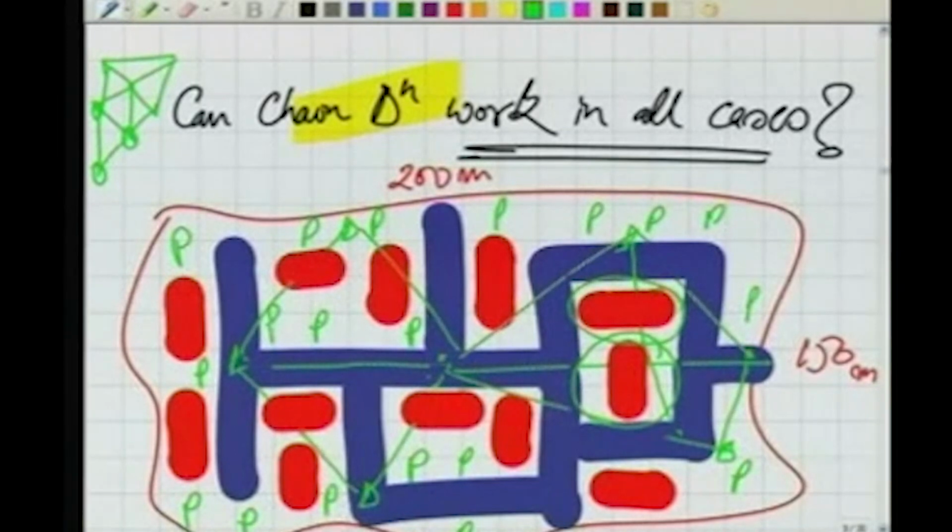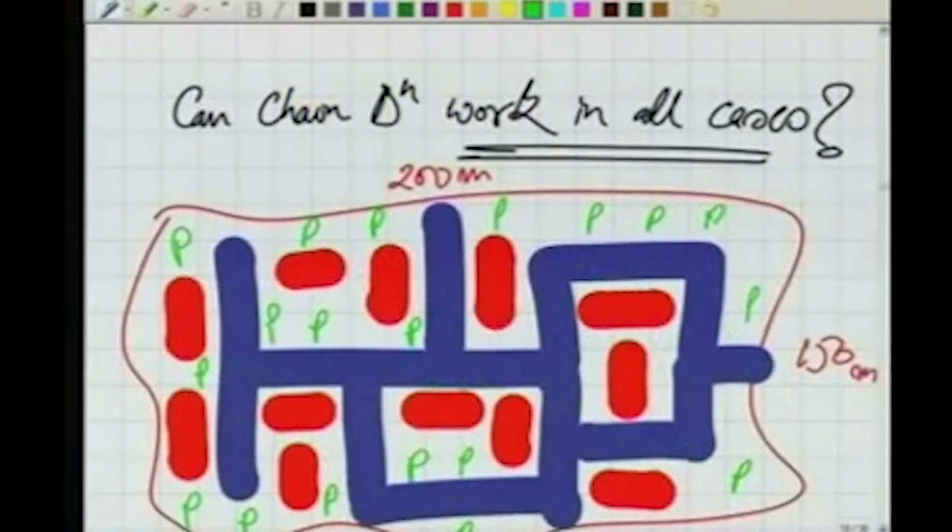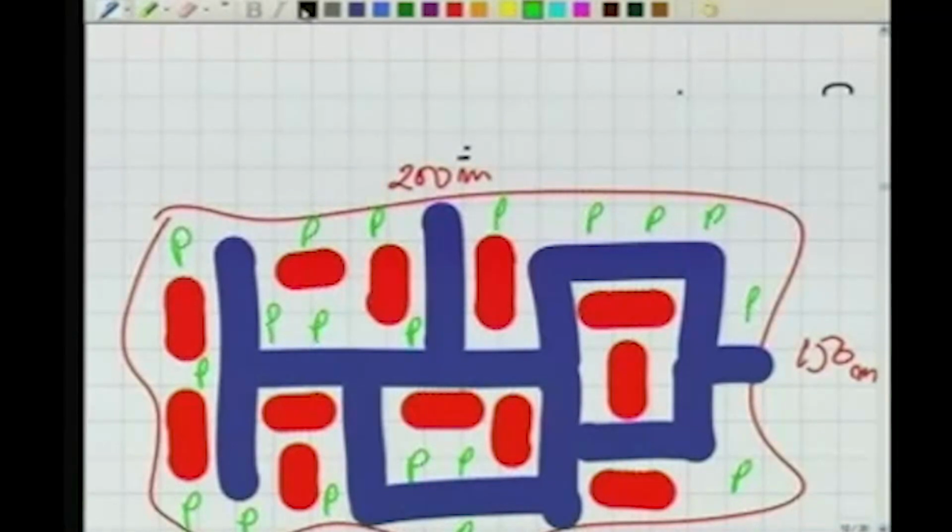Now, I have made a rough drawing here. You can think of your neighborhood, just outside the room where you are watching this video lecture. Triangulation can be done only in those areas which are flat and where visibility is clear. Only in those cases can we do triangulation, but not for an area like this. So what to do? What kind of figure can we go for? Because we need to make a map. The answer is no, we cannot do the triangulation. So what we can do, the answer lies in traverse.